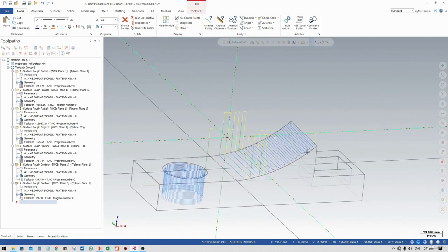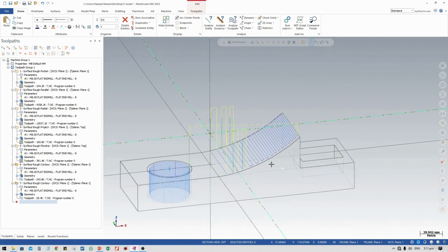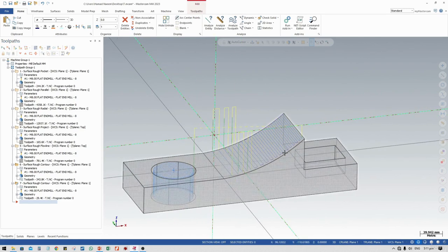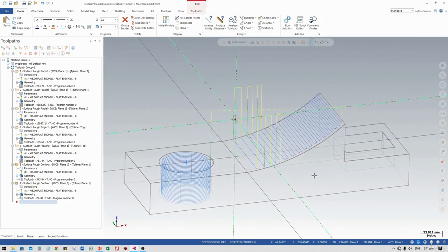This looks the same as a flow line surface area. Okay. So it just has to follow the surface. So make sure that in the contour operation, the cutter will remove the material in a very small amount because it removes the material from the peripheral side, or we can say that it removes the material tangentially to the surface which is being selected, just like this surface.